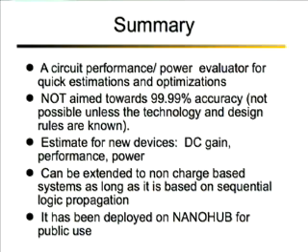Sure. The only input is the IVs, right? You don't have all the capacitors, the parasitics. I mean, the IVs is enough. Yeah, so the question is whether the IVs is enough. Yes, the IV is enough for doing the DC part of the characteristics, but for the AC part of the characteristic or the transient analysis, one has to provide the CV as well, which is essentially the intrinsic capacitor. And then you can play around with the parasitics.